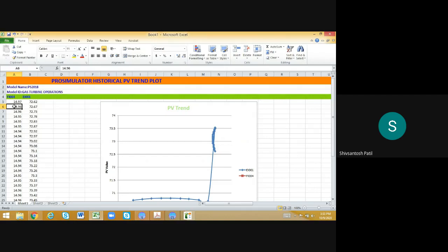So we have to be a bit careful, reduce the values slowly and increase the time span of recording the readings, because here only 5 seconds was taken. Instead, we should take a larger time like 30 seconds, and wait till all the calculation goes through. So run the whole model for 2-3 minutes and then stop the recording. This is how we have to proceed further, and you can follow these steps for all the models.